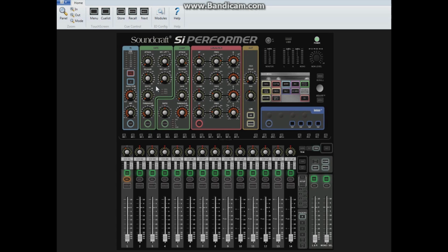It helps cut out extraneous noise, also sharpens the sense of attack for different signals, often used for kick drums in a band. Compression tends to level out overly loud signals and can be used to protect loudspeakers when it's set to its extreme as a limiter.